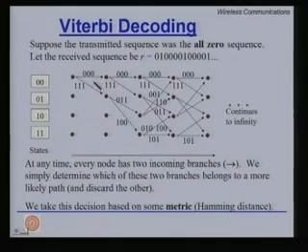So, if you go back, suppose the received vector is the following: 0, 1, 0, 0, 0, 0, and so on, 1 and so on, and for the sake of illustration only, let the all 0 vector actually be sent, and there are a few errors present. The ones represent the errors. The question is, when we pass it through the Viterbi decoder, how does it get back to the original stream that was sent?